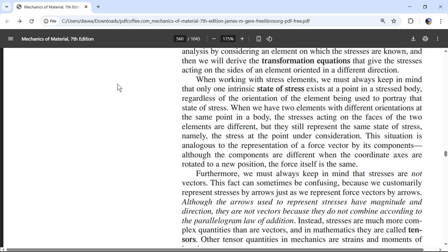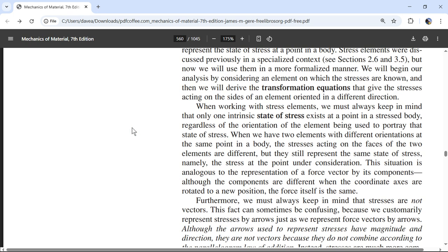And then you have shear, where the shear force is half the normal, and I'll have to look that one up again. But what this says is that if I have a square element that just has a stress this way and a stress that way, and then I draw another square, but I say it's that element at a 45. I don't have to draw it at a 45 on my paper. I can just say it's at a 45, and then I'm going to draw the stresses, shears. These two are the same, so those are the same states of stress.